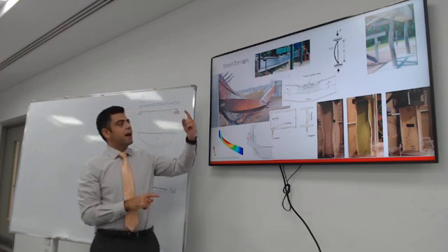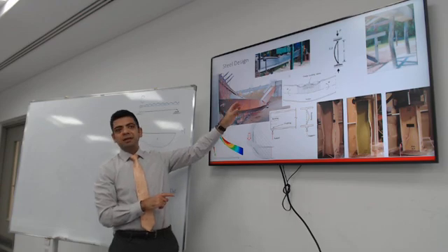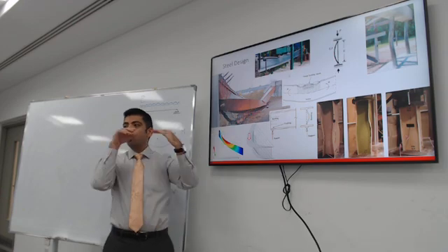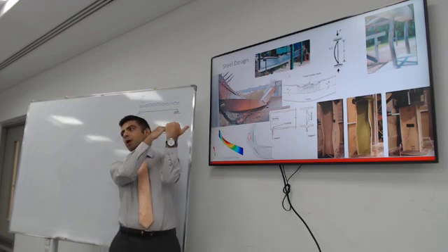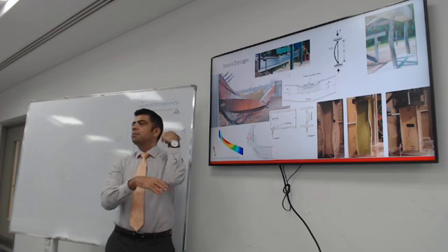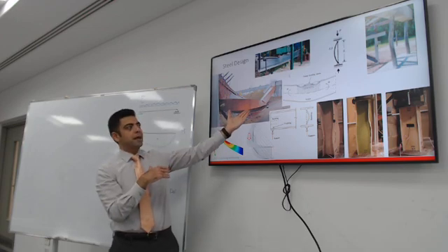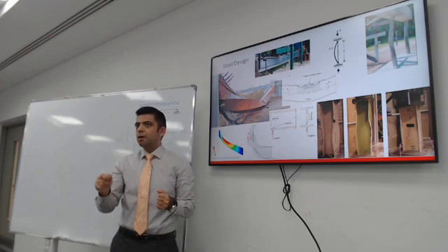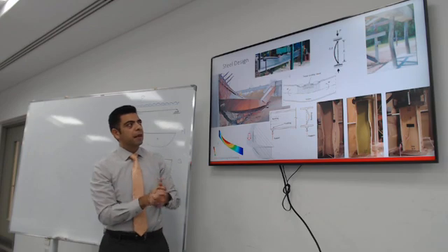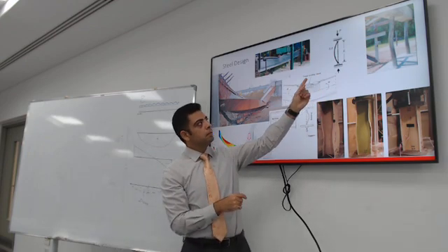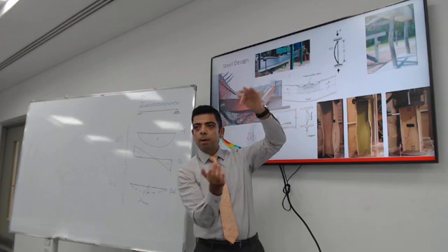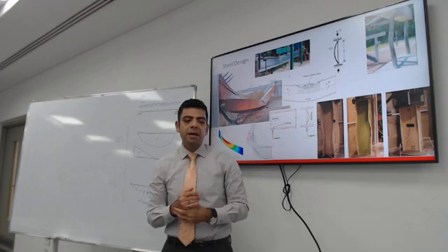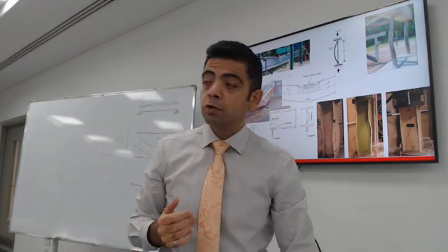First, check that the beam is strong enough to resist lateral torsional buckling. This is the type of failure where the upper flange goes sideways and the bottom flange stays in the same place. So we'll learn how to check that. And the codes, the steel code, will give you the equation. If you want the beam to be strong enough, you follow this formula, things like that. If you're designing a column, you need to make sure that it's not going to buckle. It's not going to go sideways like that, or the flanges are not going to work. And that's the essence of structural design.